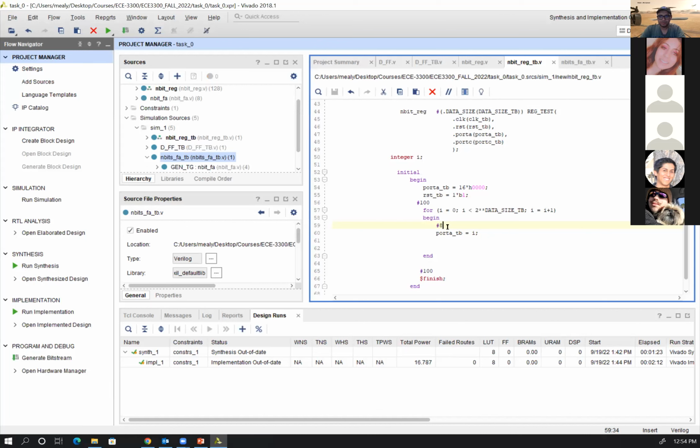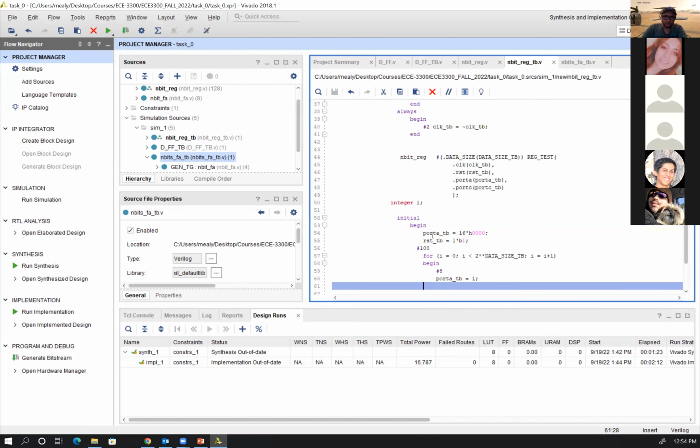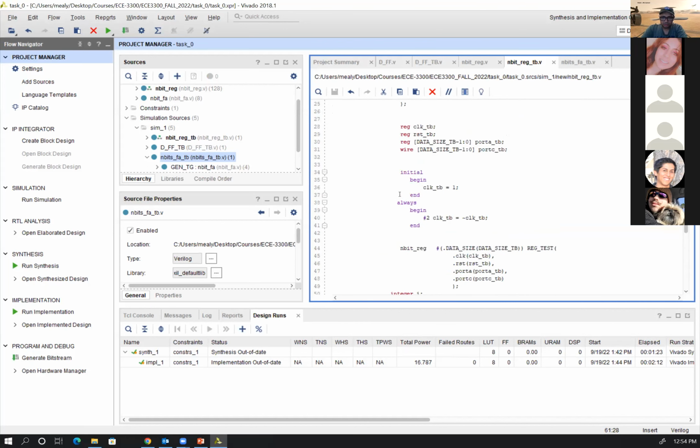You define the time first, and then you put the value. Then it will flip back again, define the time, because the for loop goes up cyclically, right? Anyway, you know what I'm doing. Let me tell you what I have done here. I generated the clock. The clock is 250 megahertz. Why? Because the duration is 2 for high, 2 for low, which means in total 4 nanoseconds.